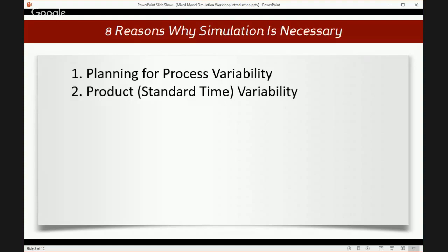And this is something that simulation modeling can be extremely helpful with, because again, you may have a very good resource calculation based on an average, but then you test it for certain mixes and you realize that a mix that you see 2, 3, 4 times a month won't be able to go through your calculated number of resources, and then you can change that, retest the model, you get better answers, you have a more solid, more reliable line design.